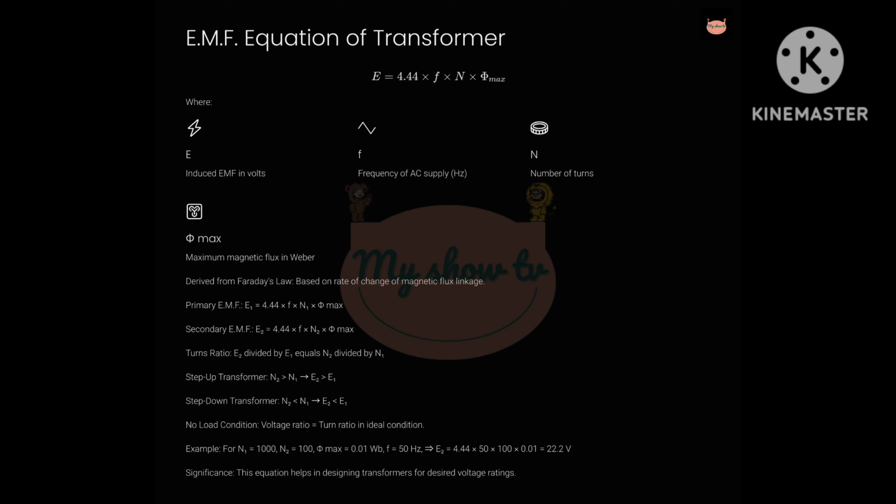5. This formula assumes ideal conditions, no core loss or leakage. 6. No load condition means the transformer is energized but there is no load connected to secondary. In this case, the voltage ratio equals the turn ratio. 7. Example problem. Suppose N1 equals 1000 turns. N2 equals 100 turns. Phi max equals 0.01 Weber. f equals 50 Hz. Then, E2 equals 4.44 times 50 times 100 times 0.01 equals 22.2 volts.